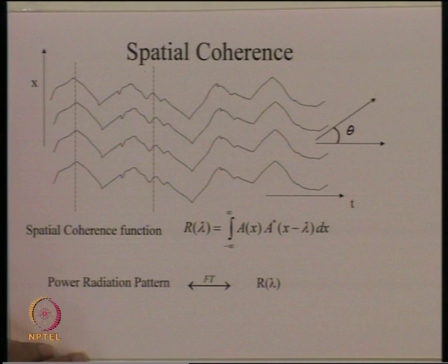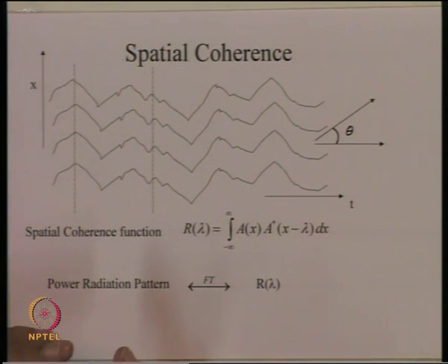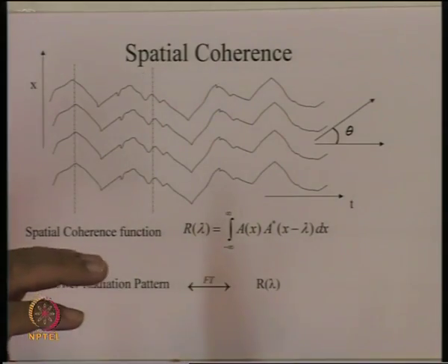So, if I make sure when the photon is born, it travels only in the direction which is within the critical angle cone, you will see that substantial improvement in the efficiency will take place. Similarly, if you have a very focused radiation or beaming radiation, then it can be launched very efficiently inside the optical fiber, because again this will lie within the numerical aperture cone of the optical fiber.